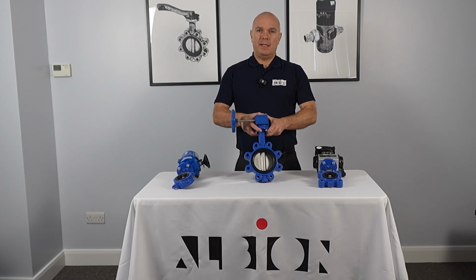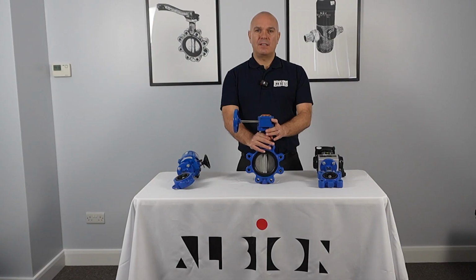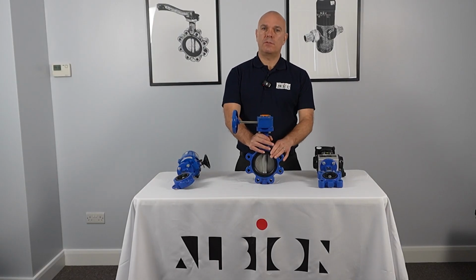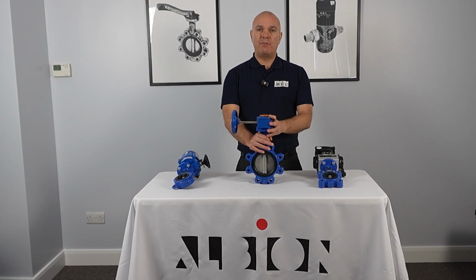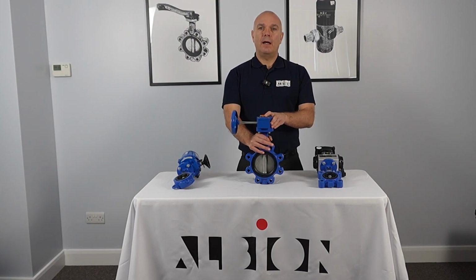Firstly, let's look at gearboxes. These can be mounted onto the top of butterfly valves where they can sit directly onto several mounting holes. The mounting holes' geometrical tolerances are taken directly from the standard ISO 5211. These gearboxes are suitable for all sizes across the range, but are particularly well suited to the larger size valves where a higher torque is required to operate the butterfly valves. Albion always suggests that for butterfly valves at 8 inch and above, a gearbox is used as this will assist with the operation.